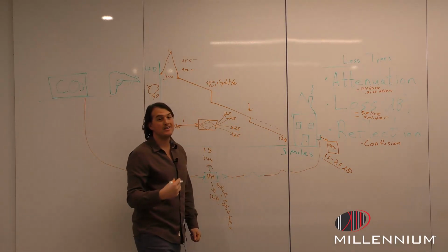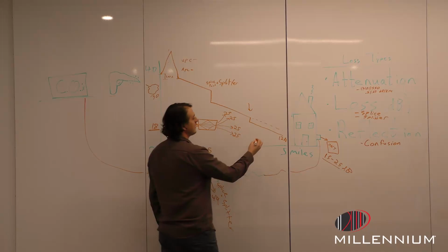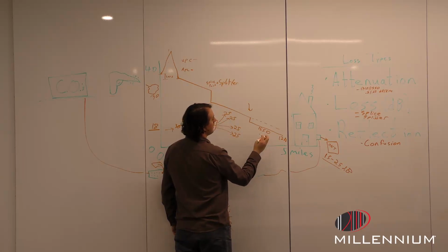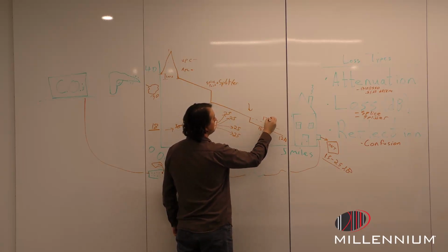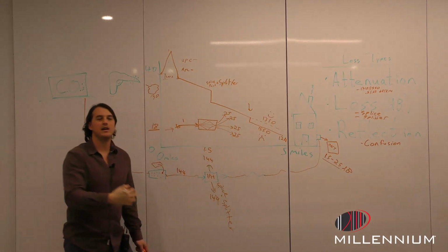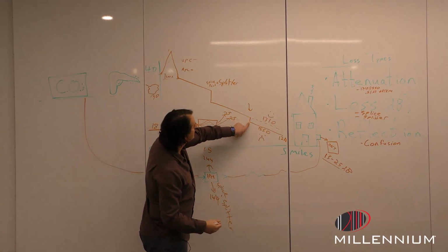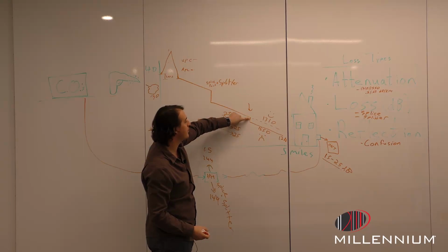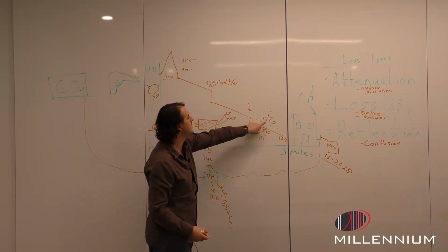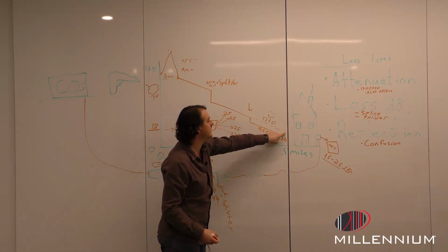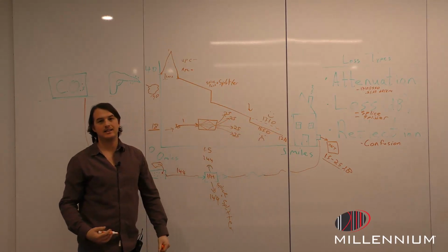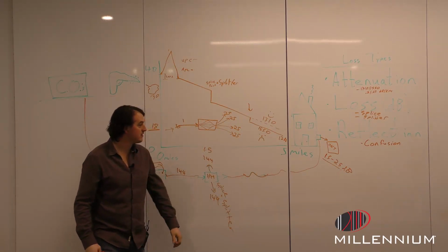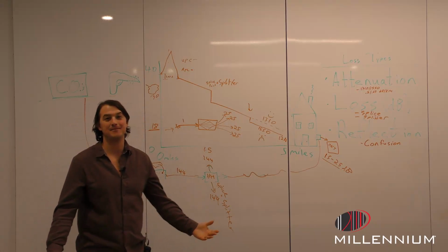So that's why we really want to test with two wavelengths, so we can spot check, because 1550 is unhappy right here. 1310 did not know any difference. But because we can reference them, this event that looks like it could be a splice, if we had only tested 1550, we might think this is a splice. But because we tested at 1310, and 1310 said it was fine, we're able to deduce that it is indeed a bend in the cable. And that is a pretty decent summary on testing principles.